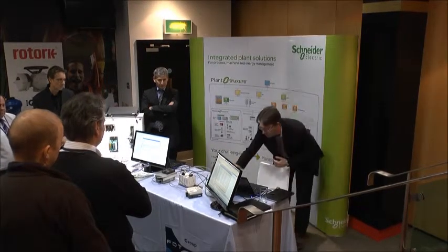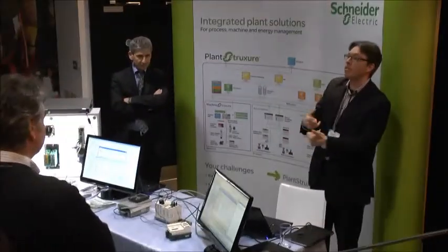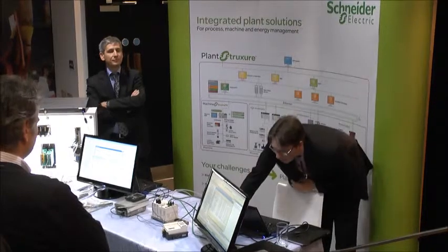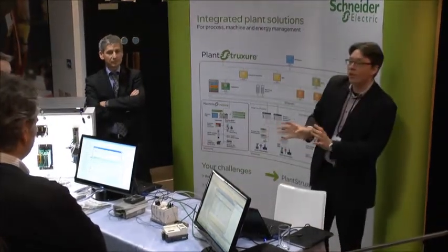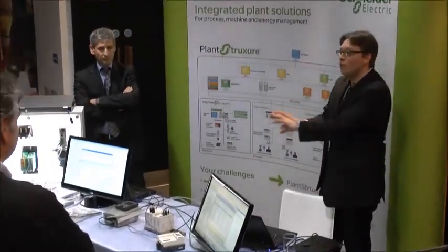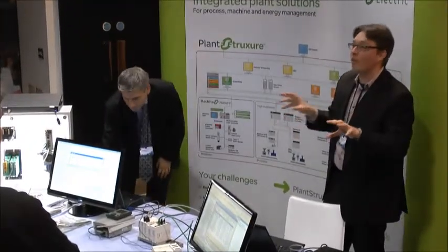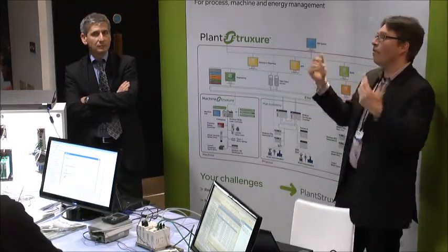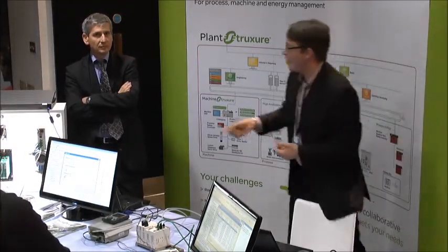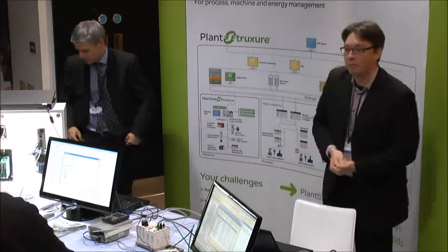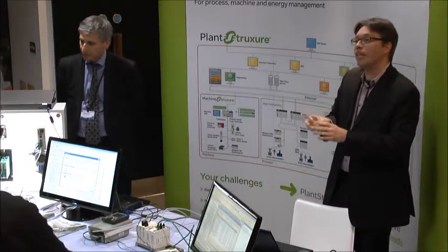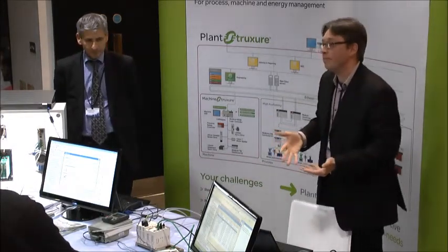Devices on Profibus, for example. First step, select the communication protocol. Here, in the Schneider catalog, the possibility to have connectivity to Profibus DP is the PRN, the Profibus Remote Master. It's a very powerful name for a gateway, but it's the gateway from Ethernet to Profibus DP. And this gateway, this PRN, is managed, of course, with a DTM.